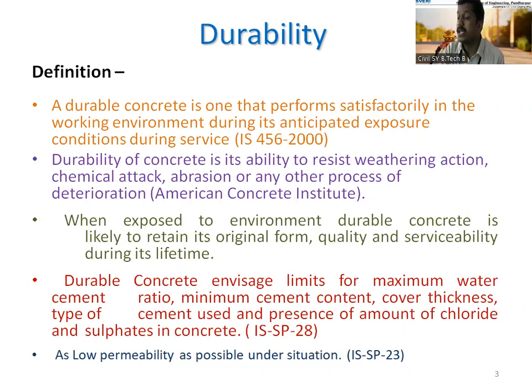Definition. Understood? Please remember this definition for a lifetime. Durability of concrete is nothing but its ability to resist the weathering action, chemical attack, or any other process of deterioration. A durable concrete is one that performs satisfactorily in the working environment during its anticipated exposure condition during its service life,